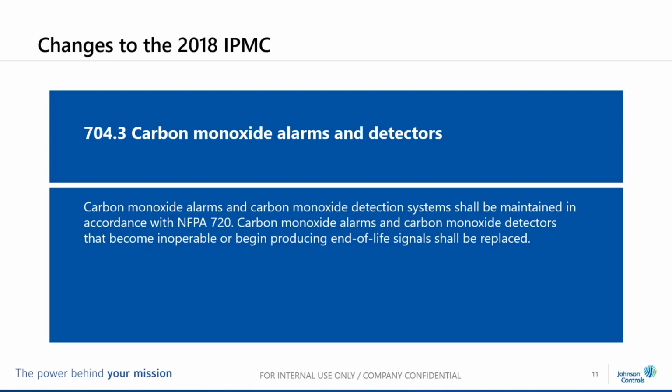And that was a study that was done by NIST, who had said, and really haven't updated this for many years now, but at the time they said the electronics, they were mainly focusing on the capacitors back in the day, that an average device could last about 10 years. And that's where the requirements came in for smoke alarms to be replaced every 10 years. With smoke detectors, again, another side note, they can be in place and can remain in place as long as the device meets the sensitivity requirements and functionally tests properly in the annual inspections. So there is no requirement of when to replace a detector, just as long as it passes the test, unlike alarms.